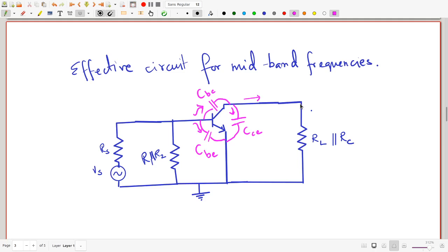These capacitors are of the order of nanofarads or so, much, much smaller, even picofarads, 10 to the minus 12 farads, that is. So at frequency ranges where the actual capacitors which you connect in the circuit behave like shorts, at the same frequency range, it's possible for these stray capacitors to have huge impedances and effectively behave like open circuits.